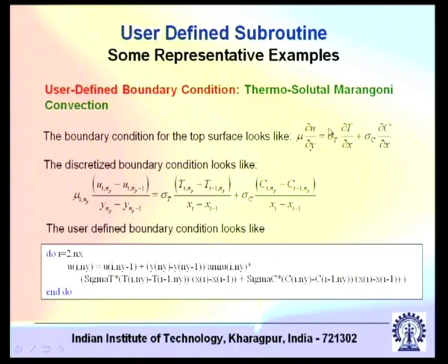This is again a stress tangential to the interface, and these two tangential stresses are balancing each other, but this tangential stress is a function of the normal gradient of velocity, that is what Newton's law of viscosity tells you. This is true only if you have V equal to 0, otherwise you have mu (del u del y plus del v del x). But if you have an interface oriented along x, you have no penetration boundary condition across the interface, so V equal to 0.